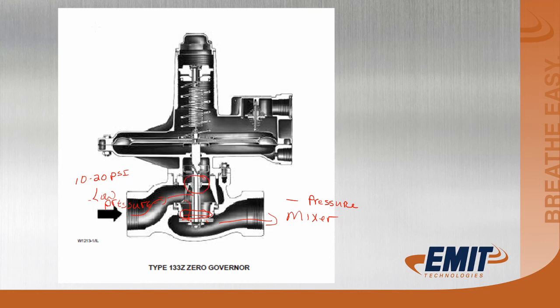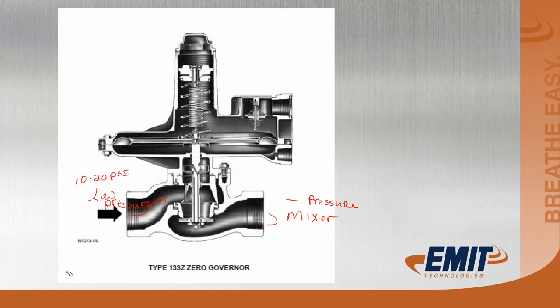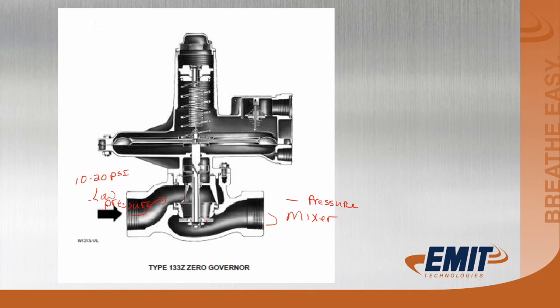This shaft is always exposed to the fuel gas, and when it's open, the debris and the varnish build up on this shaft, and then it can't close correctly, and then you have a very difficult time starting them. I've seen these shafts wedged in there where we had to take the regulator apart and drive that shaft out of there. Usually not worn out, they just get debris and varnish built up on that shaft.